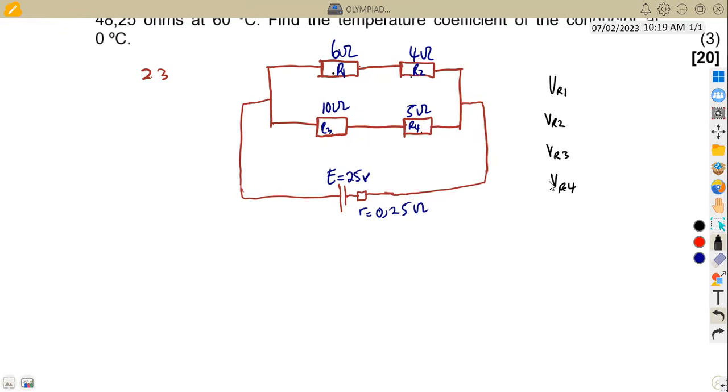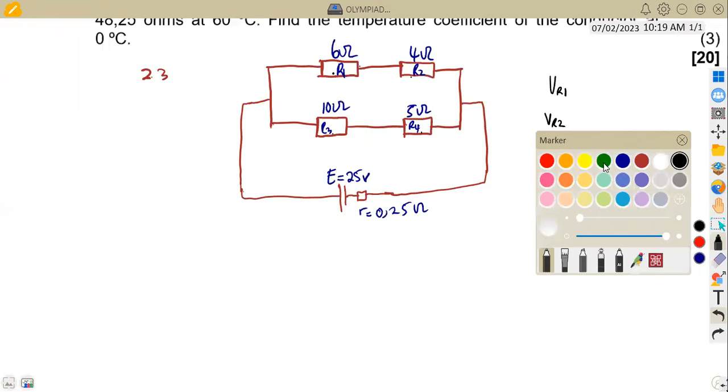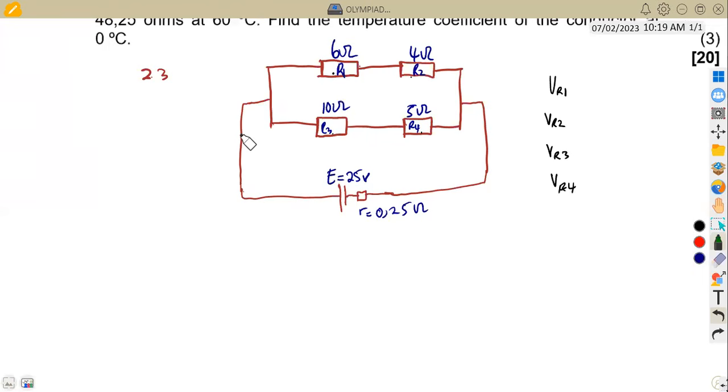All right, let us take back to our normal circuit, guys, and understand what is happening here. We know that if we can obtain the current which is flowing towards here, this current is going to branch into this branch here, and also into this branch. Let us say this is our total current. Then we can name this I1 and this I2. So if we can calculate these currents, it's easier for us to calculate the voltages, because here we are going to have a current and a resistance.